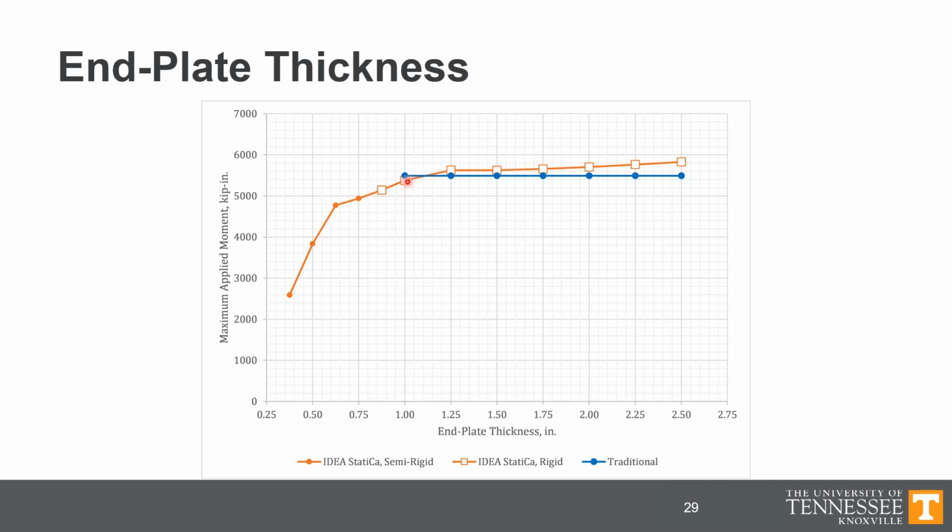As the plate becomes thick, so the other end of the graph, what you see is that the tensile strength of the bolts controls the strength. And you start to see IDEA StatiCa having higher strengths than the traditional calculations.